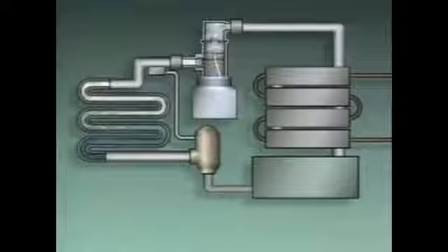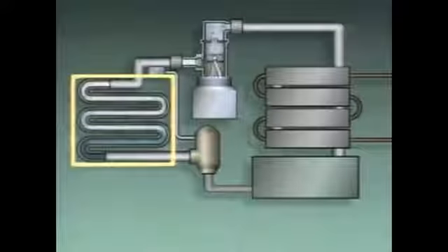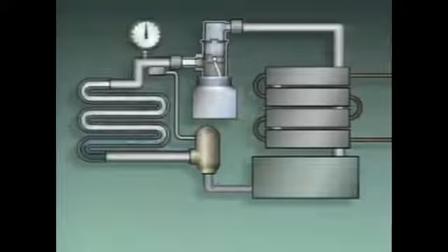One place where this is a problem is in the evaporator. When refrigerant flow through the evaporator is too low, less heat will be removed from the substance being cooled. This will cause the temperature of the substance being cooled to increase. The compressor may also provide an indication of a low flow problem. In a system with a reciprocating compressor, reduced refrigerant flow causes the pressure in the evaporator to decrease, and the control system may shut down the compressor.